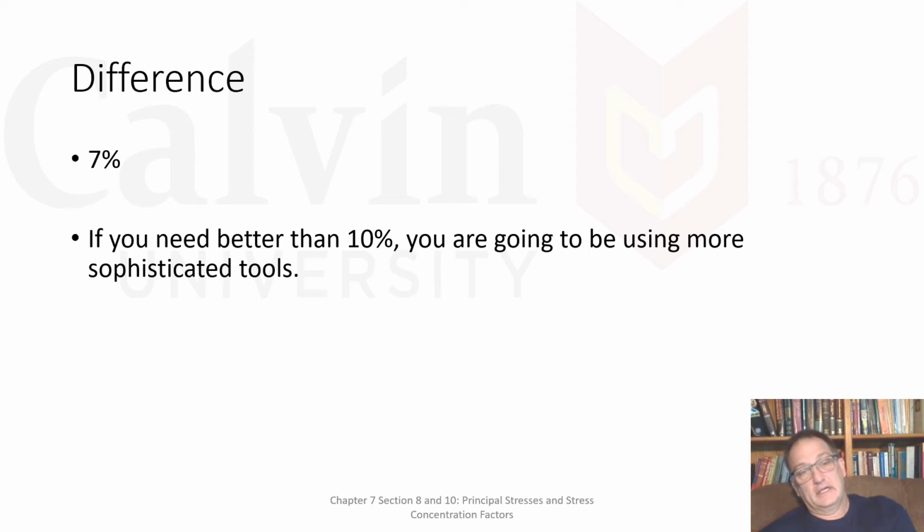If you go back and look at the systems we were looking at, our shear stresses were actually very low. They became a problem because we had wood, which had much lower material properties in the shear direction across the web. So then it was interesting. But for a normal problem, I don't think it's often a case where we're too concerned about it. So, all right, there's topic 1. Let's move to topic 2.